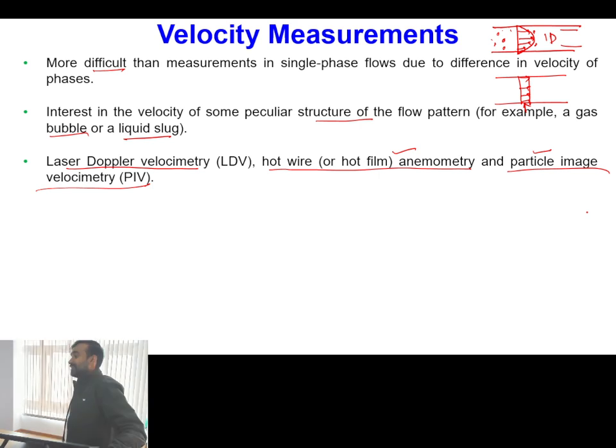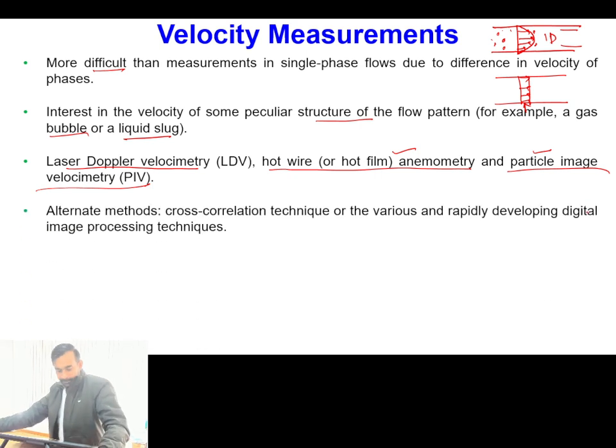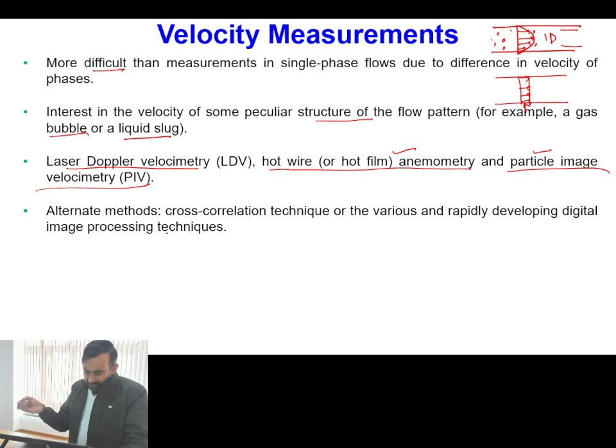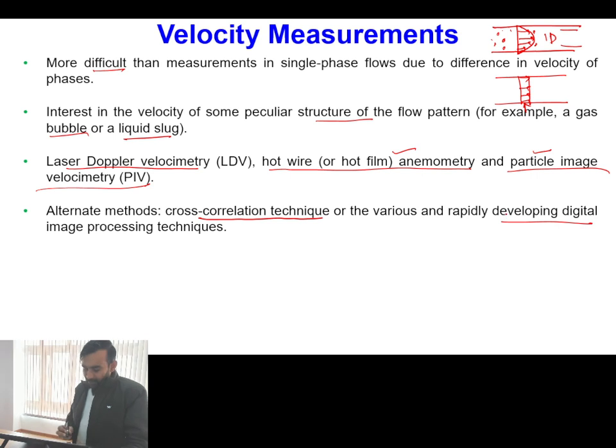Laser Doppler velocimetry is not that suitable for multi-phase flow measurements. What is the reason? Okay, there are some other alternate methods as well, such as the cross correlation technique and digital image processing techniques, etc.